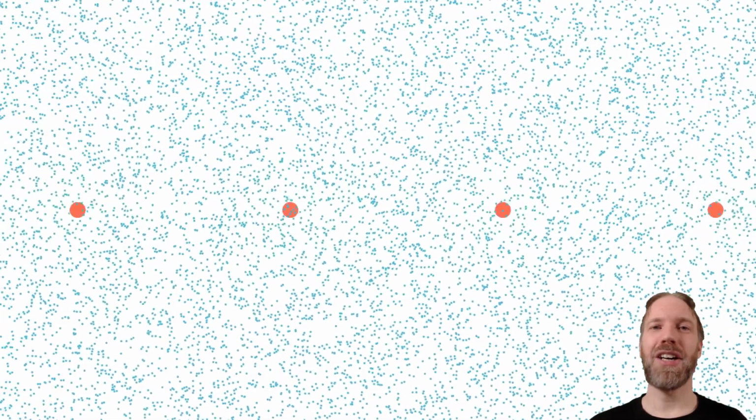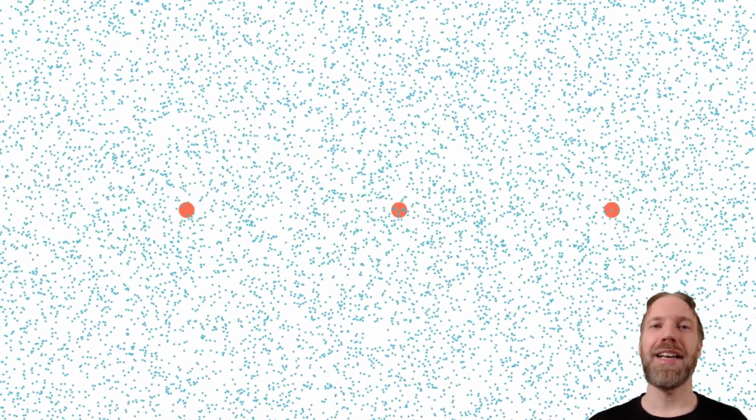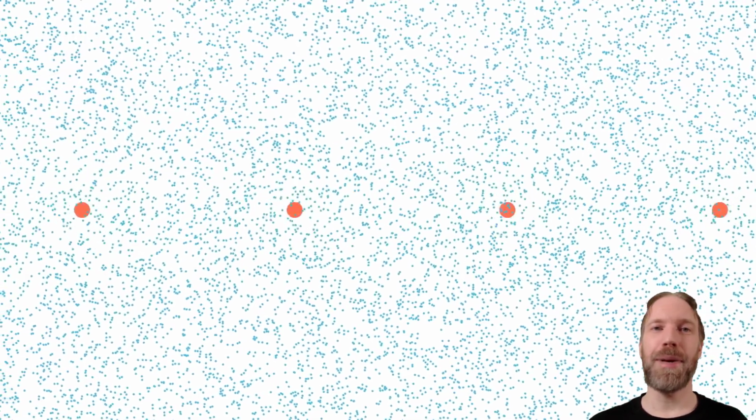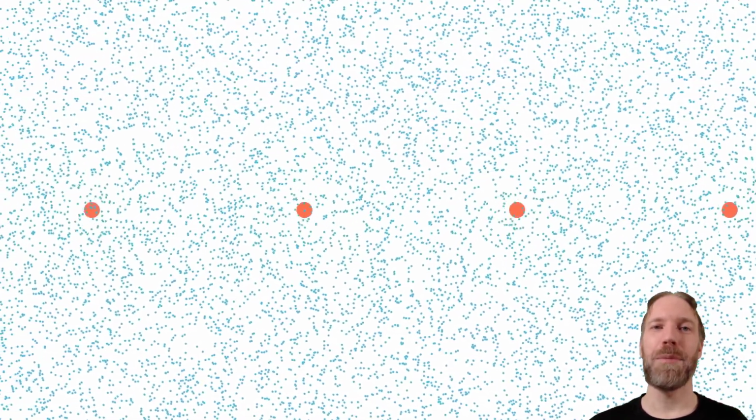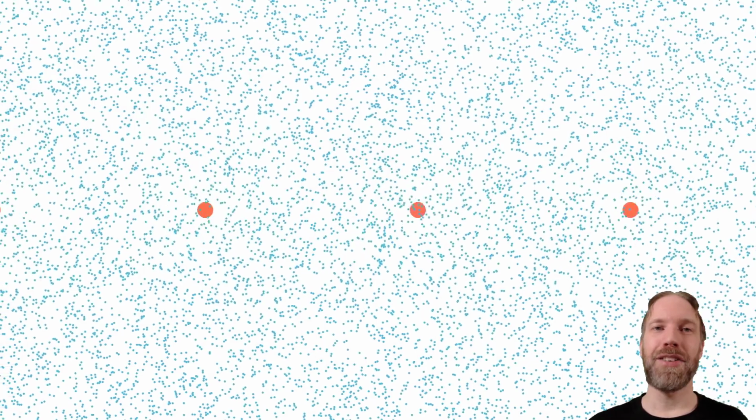To understand how vortices affect the flow, let us watch a simplified two-dimensional approximation of the tip vortices released by the blades. First, observe that the flow velocity is much larger above the vortices than below. Hence, tip vortices can be used to describe the reduction in flow velocity in the wind turbine wake.